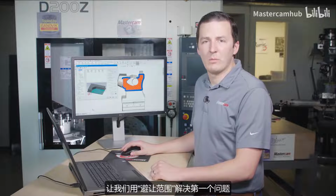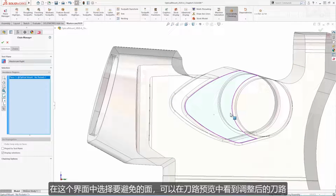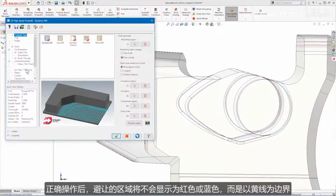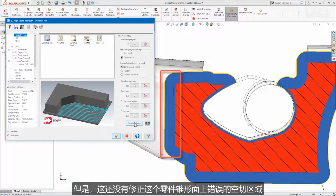Let's solve the first problem with an avoidance region. By selecting the faces to avoid in this interface, the toolpath preview will adjust. Done correctly, the area to avoid will not be red or blue, and it will be bounded by a yellow line. However, this does not fix the false air region on the tapered face of this part.